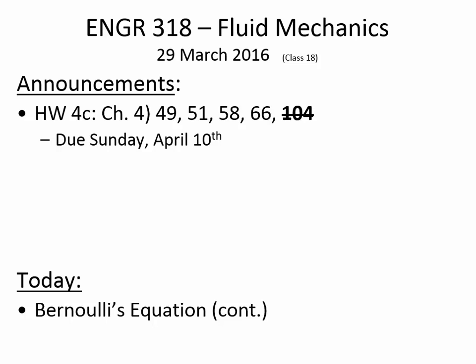Okay, so it's a change in velocity that is relating to the change in pressure and the change in elevation. What kind of change in velocity? Maybe the clue is in the limitations when we were saying it's for an inviscid fluid, which is incompressible, along a streamline, and then the last one is steady flow. Bernoulli's equation should be applied for steady flow. What was the difference between the type of acceleration for Euler's and Bernoulli's? Okay, convective acceleration is for this one, and local acceleration was for Euler's equation.